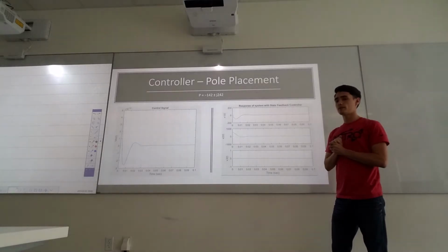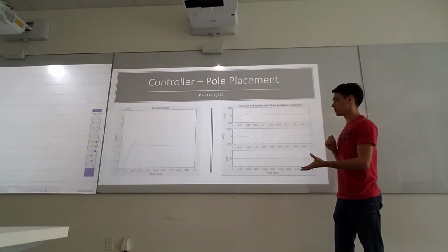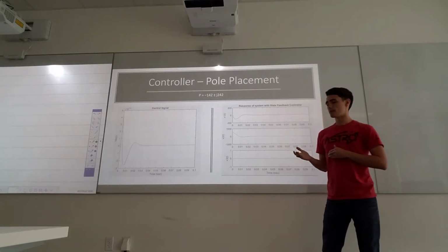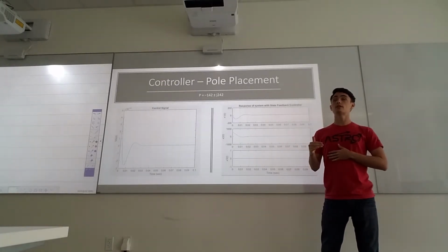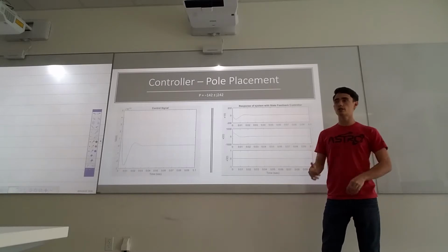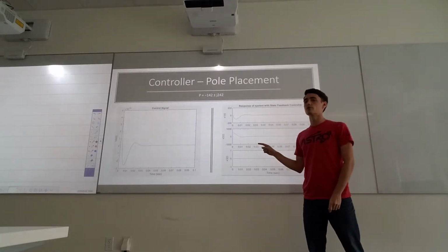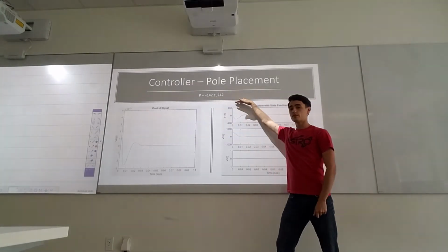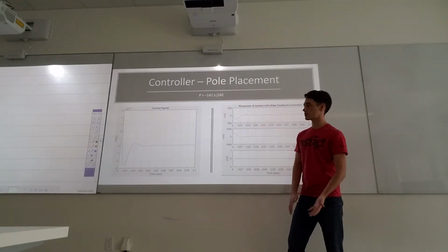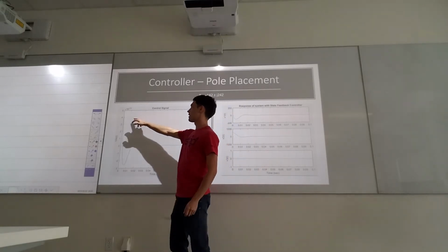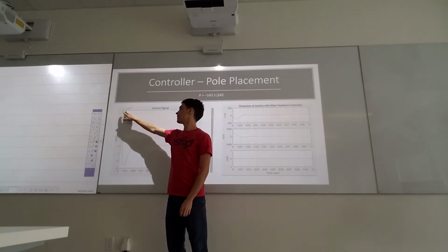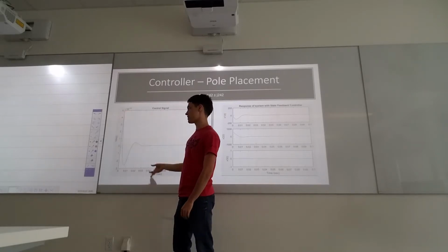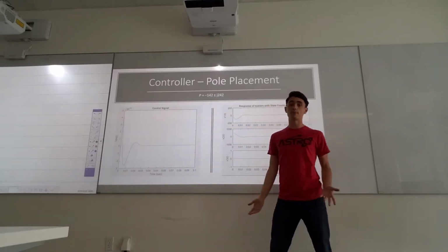Since we were using state feedback, we chose some poles to see how the system would respond. And to do these simulations, we just used initial conditions and watched the response back down to a 0 steady state. These were actually the original poles of the system, so this is the natural response with no control signal. And you can see that here, our control signal amplitude is in the 10 to the negative 13 range, so that's almost nothing. You're not using any energy, and that's because you don't have to compensate for anything in the system.